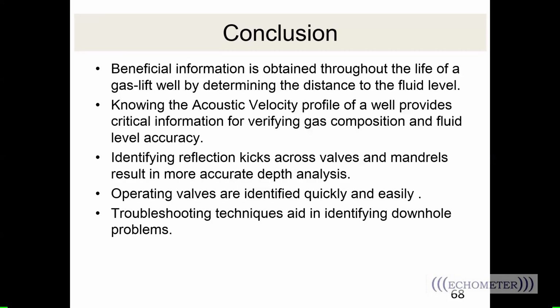All right, so beneficial information is obtained throughout the life of a gas lift well. Knowing the acoustic velocity profile of a well is going to help you make sure you've got a good quality shot. It's going to help make sure that you've got an accurate fluid level shot, also just to verify your gas composition. Identifying reflection kicks across valves and mandrels results in a more accurate depth analysis. Operating valves are quickly and easily identified, especially using TAM and that wellbore overlay.